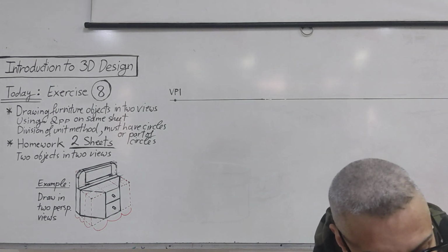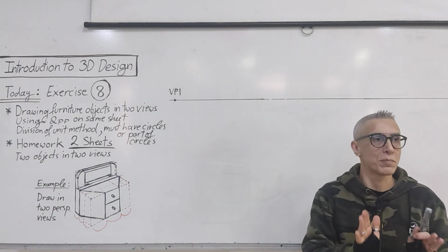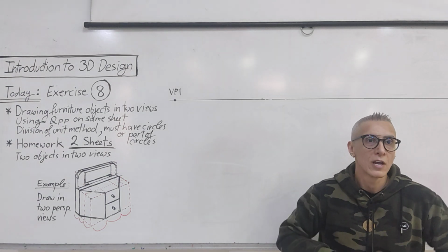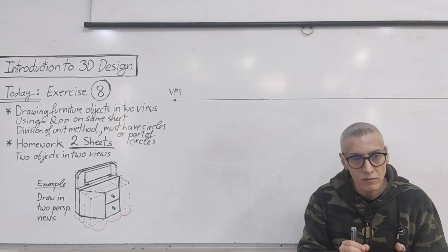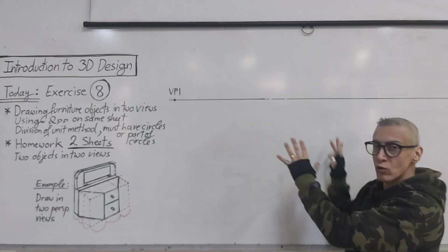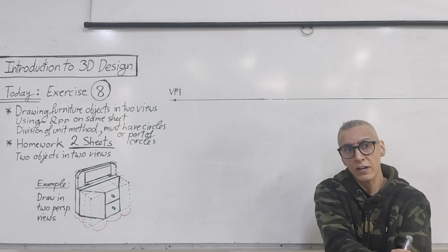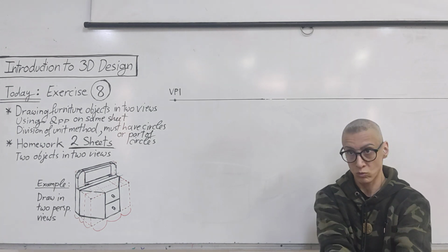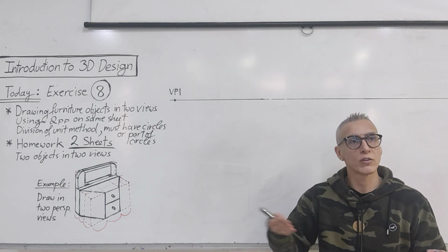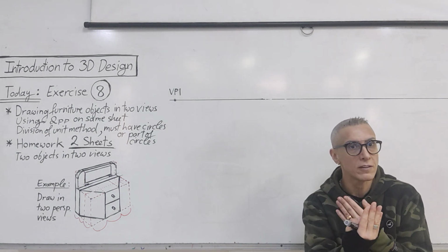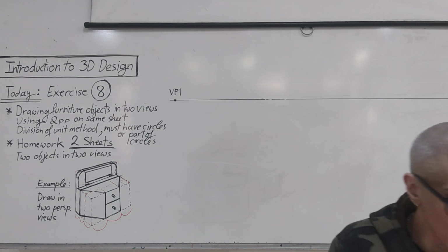All the construction lines, these many lines that I draw to construct something, must be on the paper. If it's not on the paper, it's copied for me, and I will not put a mark, okay? So please, the method that we learned, very light lines for the construction, so that when it gets overcrowded with lines, you can still draw the dark lines for the object that you want to keep, to stand out. So, light lines, heavy lines, all of these things, dotted lines, if you have something hidden from the back, you must apply this. And everything must be on the paper. Any questions?